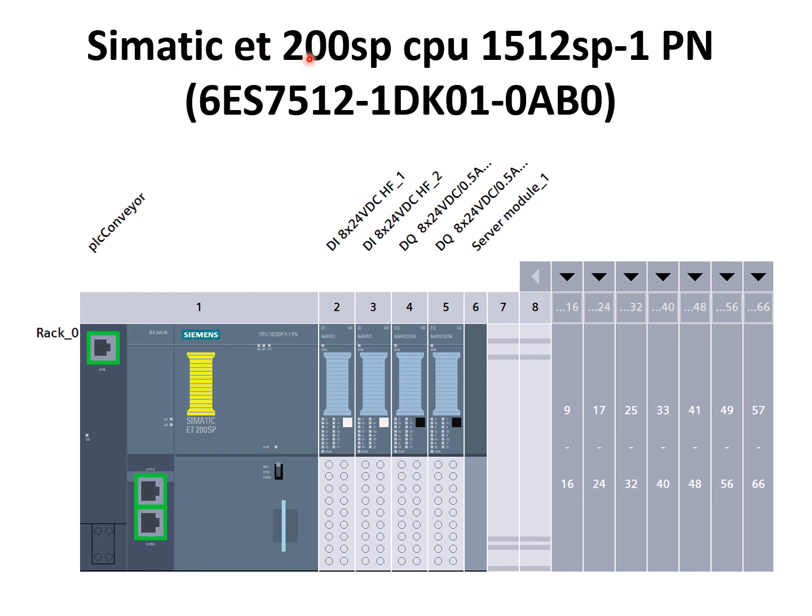schematic, ET200 SP CPU, and we added 2 input modules and 2 output modules. Why exactly 2? Because we want to match our program with the real hardware that we have on MPS 500 systems inside the lab. Inside the lab, the PLC is equipped with 2 input modules and 2 output modules, each accepting 8 inputs or outputs.